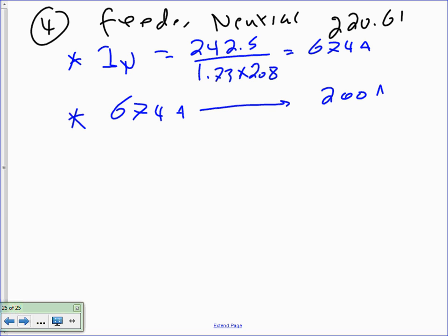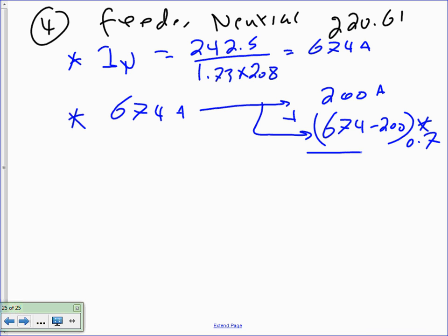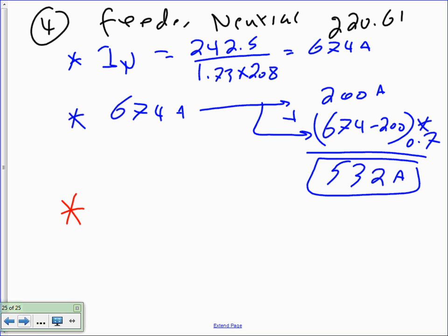What do you do with them? Don't you ever mess with them. Higher than this: 674 minus 200. You multiply this by what? 0.7. And who's my favorite student for the day? Who's going to give me the answer? 531.8. 532 amps. Thank you. Now that I derated the neutral, I have 532 amps.